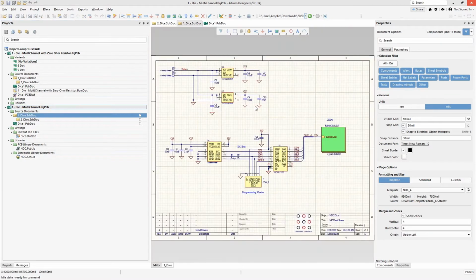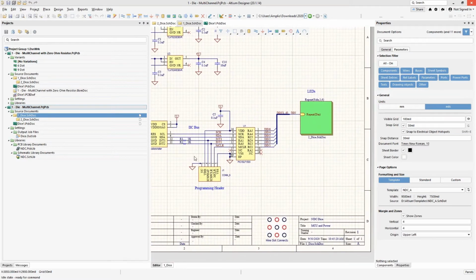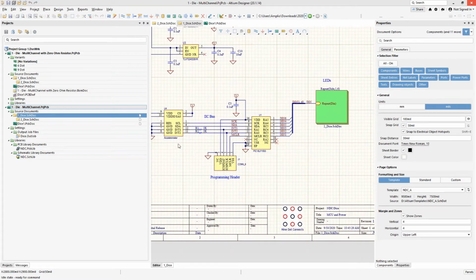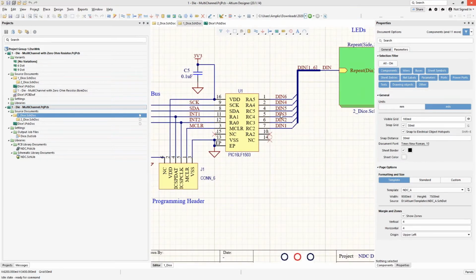So this is the schematic for this die. To just give you the 10-second tour of it, we have an accelerometer, and we've got a simple PIC chip, which has basically one set of buses here, which are broken down to individual bits. So when this thing gets rolled, it's not an altimeter, it's an accelerometer. The accelerometer will determine which end is up, and then it will display the appropriate numbers. The number is going to be randomly generated, at least in the original, from 0 through 9, and each of that information is put through each one of these lines here.